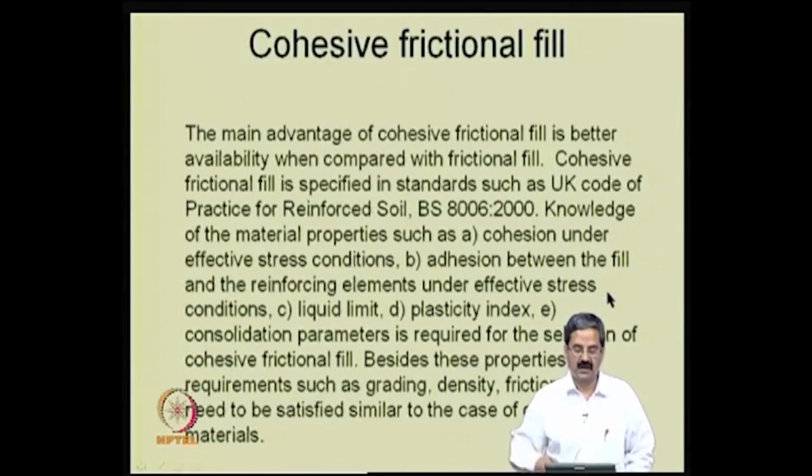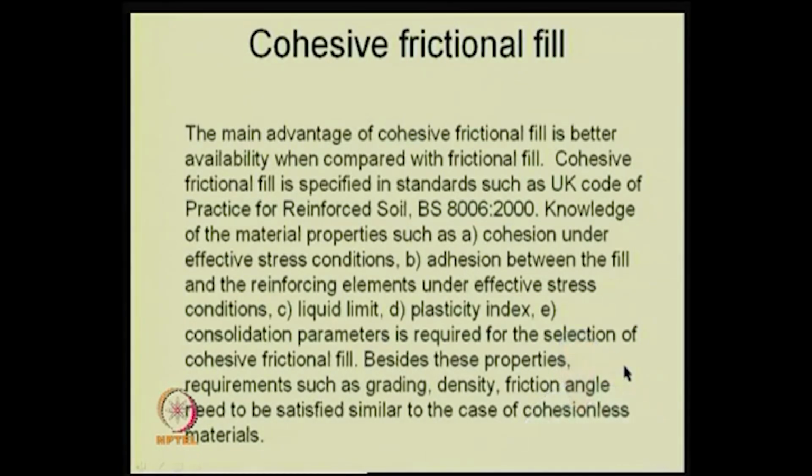And sometimes, if sand is not available, a cohesive soil is also acceptable, but there are some requirements that it should not have too much liquid limit and plasticity index. There are some specifications that are given, and again all of these things are standard. For example, you should find out c and friction angle and all those parameters, and make sure that it will not lead to any other difficulty. For example, you can't take an expansive soil as a backfill material. You have to choose a backfill material that has a small cohesion and also gives enough frictional properties, okay.